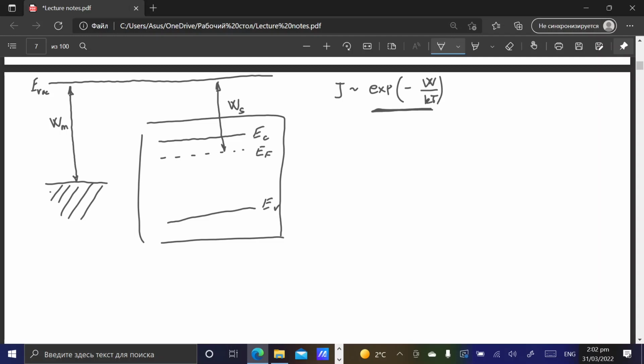to that extent that they will become equal, and there will be thermal equilibrium, which by definition also means that Fermi energy level for metal and semiconductor should be the same. So when systems with charge carriers are in thermal equilibrium, there should be the same Fermi energy level for both systems. So now, taking this all into account, let us consider how the band diagram will look